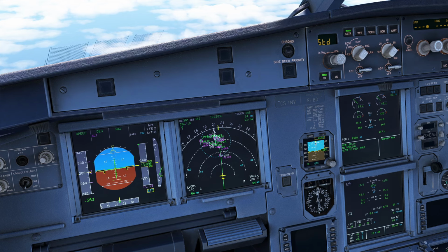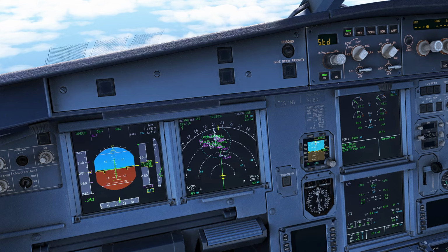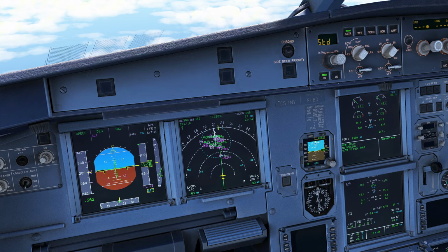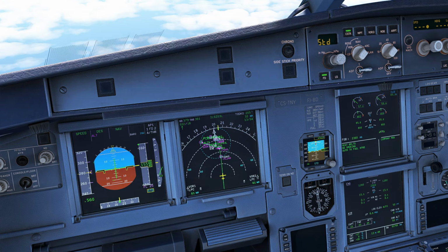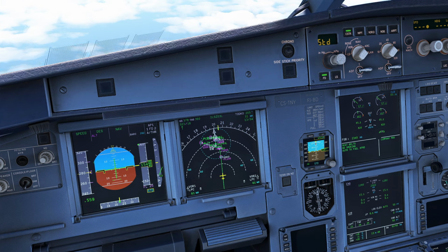The stabilization point for the decelerated approach should be by 1000 feet AGL in IMC, or 1500 according to airline SOP. But for the early stabilized approach, you should be stabilized and also in full configuration before 1000 or 1500 feet AGL.